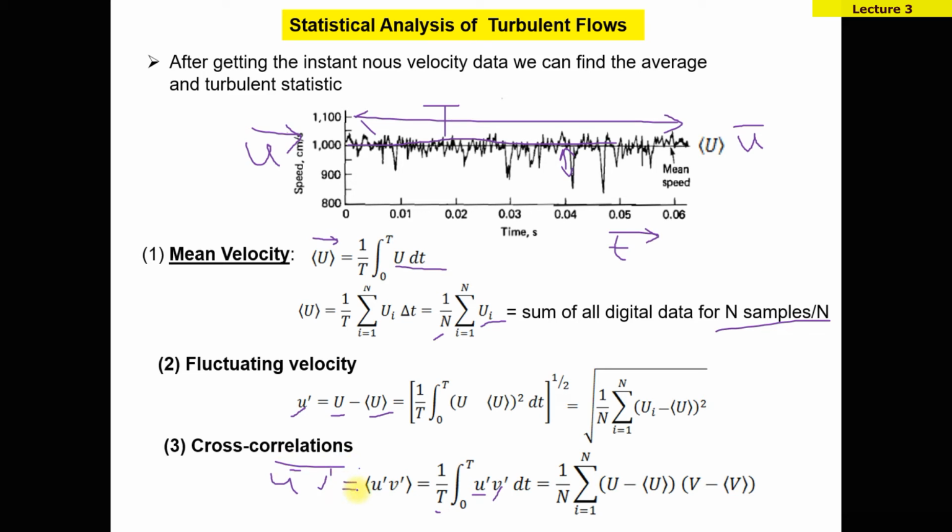Similarly, we can find the turbulent heat flux like u dash T dash, temperature. Similarly, we can also count the mass flux for turbulent flow or any scalar quantity. That's possible in experiment, and this value can be compared with CFD simulation to validate the turbulence model.